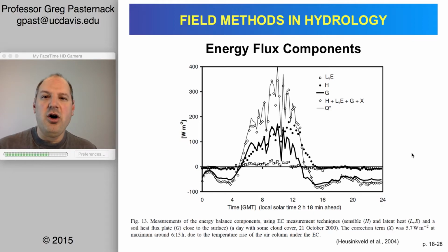So overall, what we've covered in this presentation are direct measurements to get at evaporation, like the flux equation, I should say, by looking at the gradient in moisture with height above the ground. We've looked at pan evaporation, atmometer. What else did we do? We had the lake evaporation with the empirical equation, right?